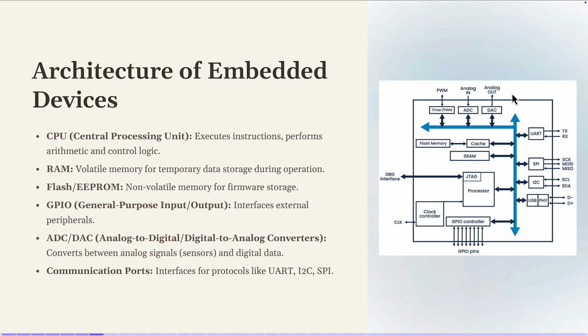First of all, there is no interfacing with the GPIO. It can be connected maybe through the USB, but if it is USB 2, it will be slow. And there are other types of interfaces like SPI, where it can be connected and provide much higher bandwidth and data rates for exchanging data between the board and the SSD hard drive. Voila. Other questions? Okay.